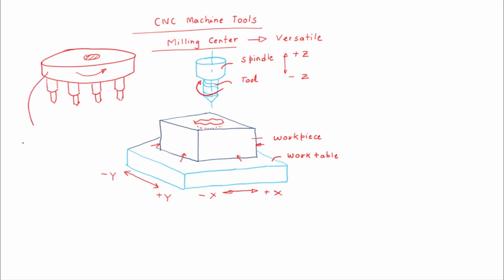So this is the tool umbrella, tool storage. As per the need, to change the tool, we need a certain mechanism. That mechanism may be unloading of the tool from the spindle, taking that unloaded tool to the umbrella and keeping it at its predefined position. Then taking the new tool from the umbrella and transferring that tool to the spindle location, loading that tool to the spindle.